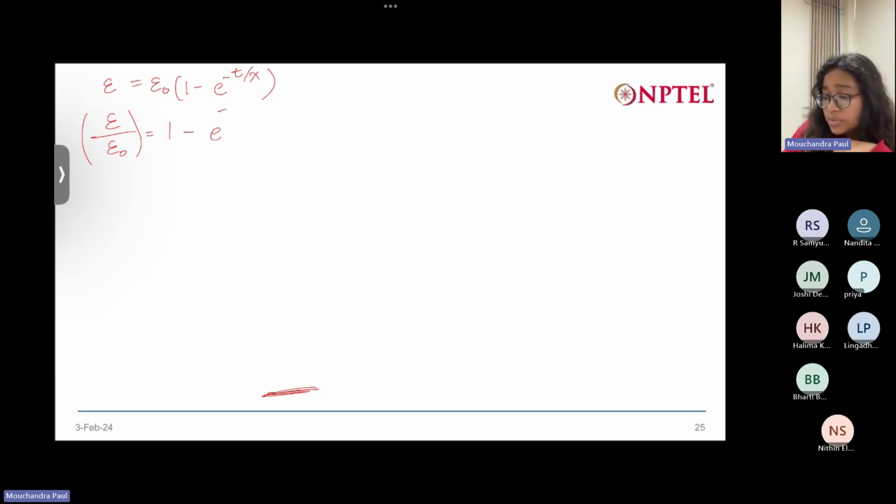So in this part B, what is t? T is 6 hours. What is the value of lambda? Just now we have got. Now see, lambda will not change. Logically, lambda will not change for a particular type of material. If say you made a tube out of PVA, it has a retardation time of say 11.6 hours. Then no matter how long you check it, say after 10 hours, 12 hours, it will stay the same. It's like a unique signature of a particular type of material.